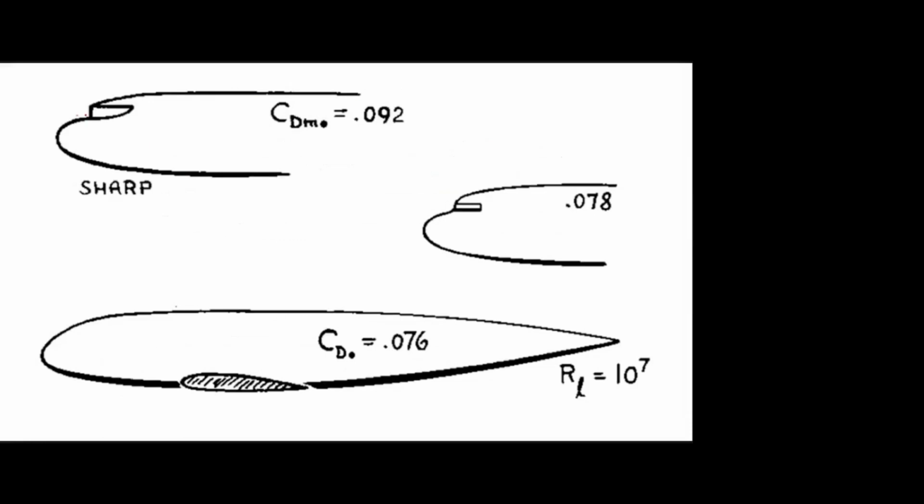Same concept. Here it is a sharp corner, it is 0.092. Here it is a little bit smoother, 0.072. Nowadays we don't see this bulge. Everything is merged into the streamline shape, so it is reduced to 0.07. So now it is a single shape like an aerofoil shape.